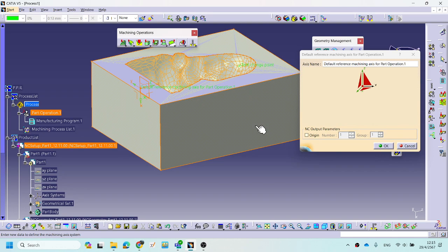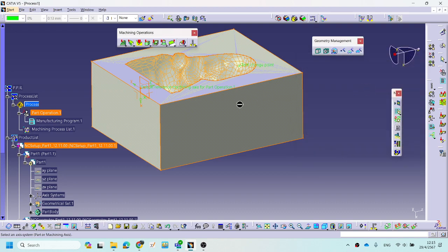And to part: generate the tool path. It is different with this axis. Okay, this axis, you need to define this axis, that is the reference of the tool path, the reference of the G code, right? Okay, this is the start point, the 0 point. Define the 0 point, click on center, right? And click on this edge.